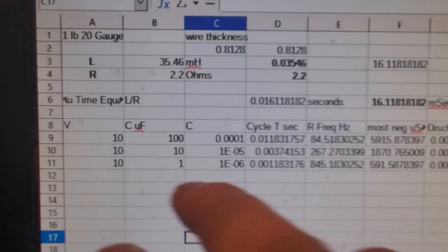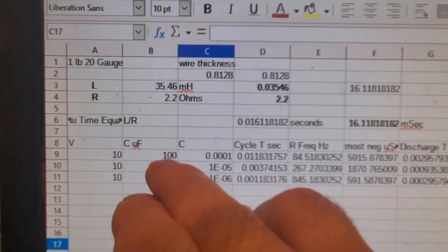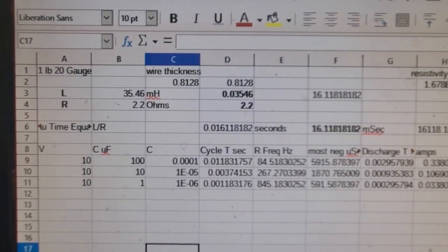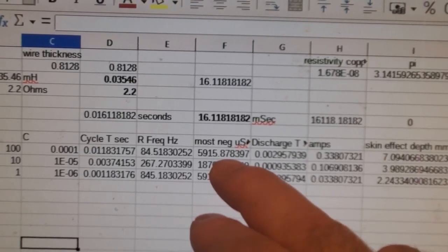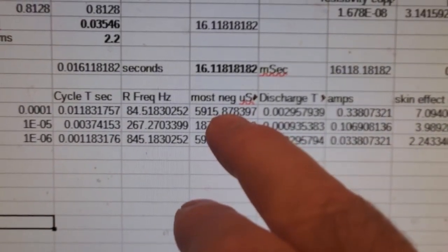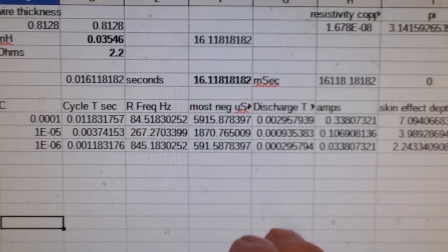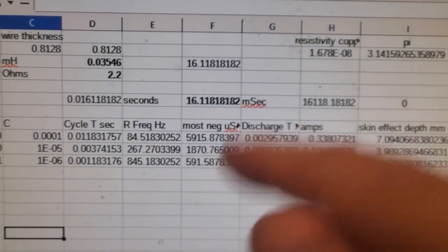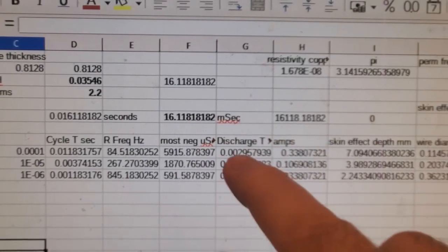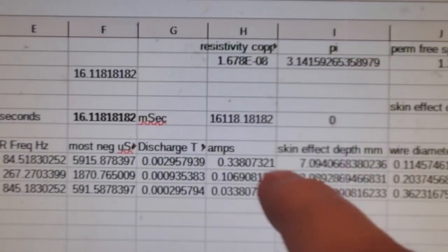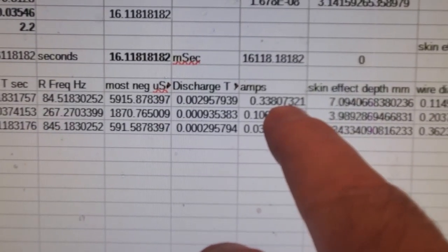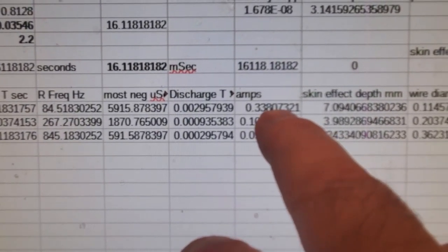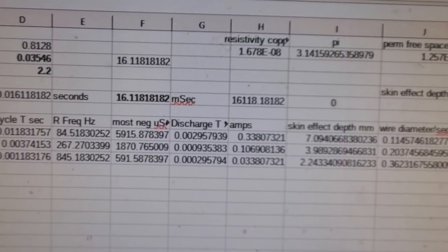And you wouldn't think it. You know, you have just this little 100 uF cap, and you're at 30 volts. You know, oh, it can handle that. No, it can't. Now, if this were quicker, then if you got down, instead of it being say 3 milliseconds, that it's discharging down like 1 millisecond, it can handle a pulse a little bit better. But you wouldn't want to go over 10 volts with a 100 uF cap, or you're in danger. Certainly you wouldn't want to go over 20, or you'll probably blow the thing up. So that's what that is just to keep that straight.